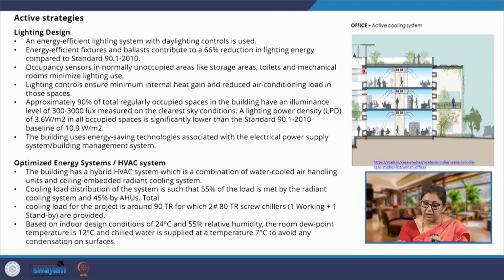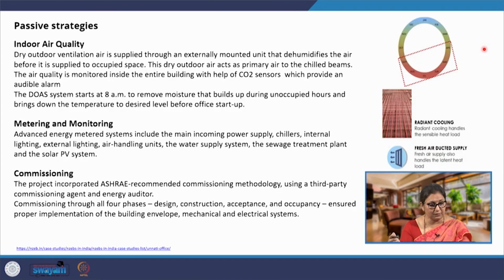The windows, and we also see that there is a light shelf which has been provided. So, if you look at this, there is a vision glazing and there is a light glazing with light shelf. So, the entire space gets properly daylit and the ventilation also happens properly. So, enhanced ventilation strategies, more efficient lighting design. Before these two, before more of the mechanical and electrical systems, the building design has been done properly.